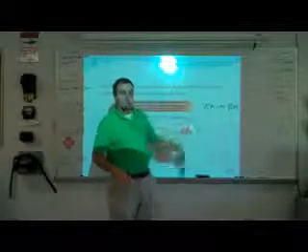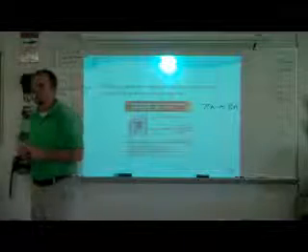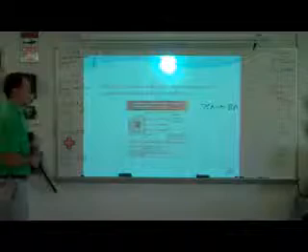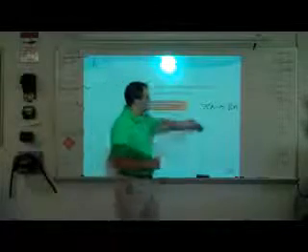Anything 800 amps or below, if you do your calculations, you figure out, okay, this motor and this motor added together comes up to 75 amps, and you go to the next size bigger. Okay, so that's what that's saying. 800 amps or larger do not correspond to standard size or then rounded down. Okay, I doubt you guys will ever see anything over 800 amps.